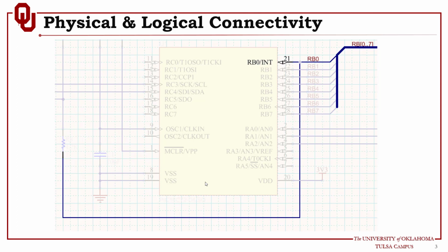Basically, on a schematic design, you can create connectivity by drawing a wire from one component, in this case this resistor, all the way to the other component or the pin of the other component. Like here we have I/O for a microcontroller. This is referred to as physical connectivity because you have a physical connection between the two components or the pins of the two components.